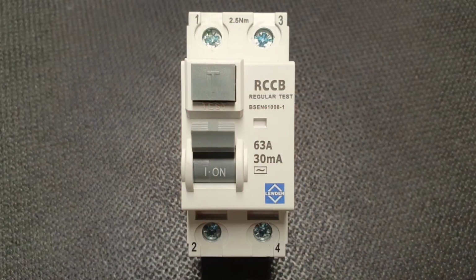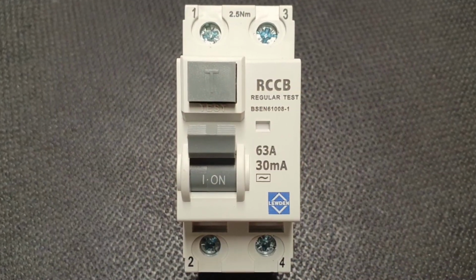Well, if our installations connect the loads we discussed earlier in the video, then it's likely that our old AC type RCDs won't operate under fault conditions. And that means that someone could be receiving a lethal amount of electricity through their bodies and the RCD simply won't disconnect the circuit. There is a second problem as well.